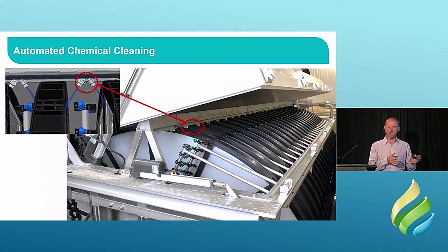This is not possible with the outside-in design. This is a feature of the inside-out design, that you can keep the system online, the filtering, because you're putting such little chemical in to do the cleaning that it is not a problem in terms of discharging chlorine. It's going to get neutralized because there's so little of it, and there's such a lot of dilution going through, and other things that are going to bind up that chlorine before it goes out into the river.